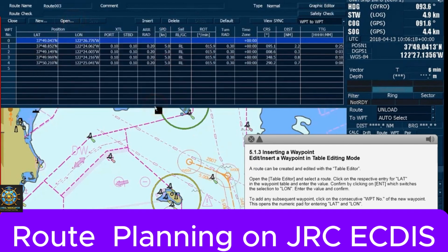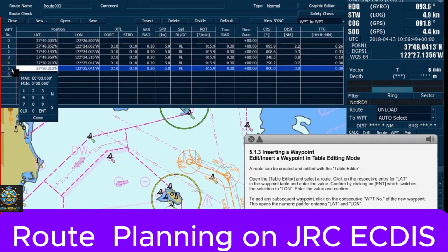Click on the respective entry for latitude in the waypoint table, and enter the value. Confirm by clicking on Enter, which switches the selection to longitude. Enter the value and confirm. To add any subsequent waypoint, click on the consecutive waypoint number of the new waypoint. This opens the numeric pad for entering latitude and longitude.